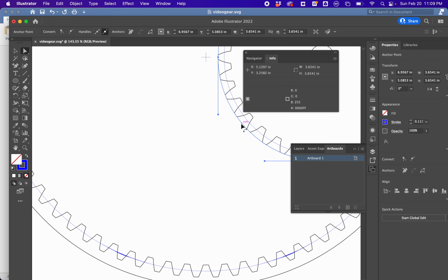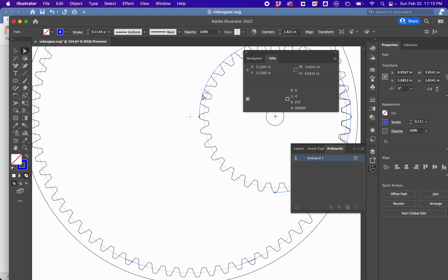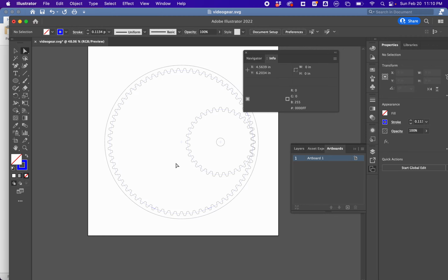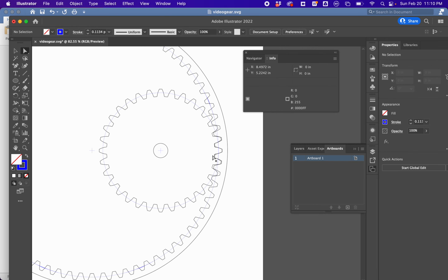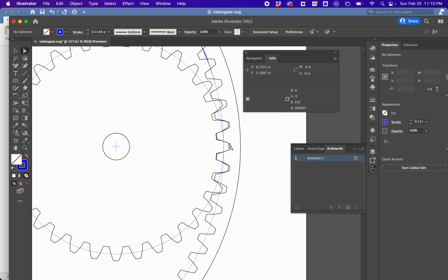Okay. The only one that we really need right now for any reason is the middle line on the small gear. But I'll leave the middle line on the larger gear for just a moment to show you, when we think about the gears rolling around each other, it is those blue lines, that middle blue line that's going to be rolling, adjacent, right, touching the inner gear and the outer gear. So those are the 2 lines that we're interested in. Those are called the pitch lines.